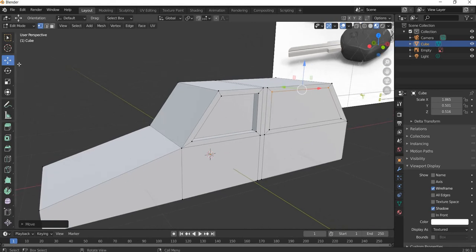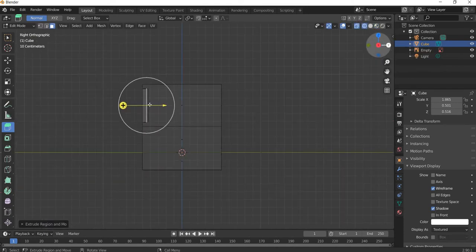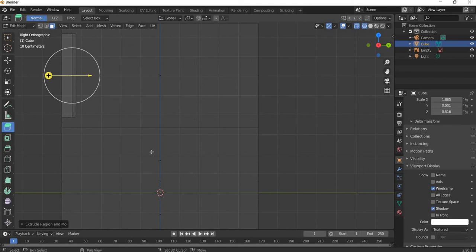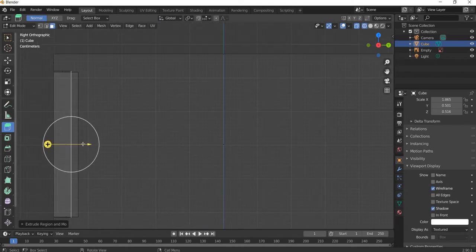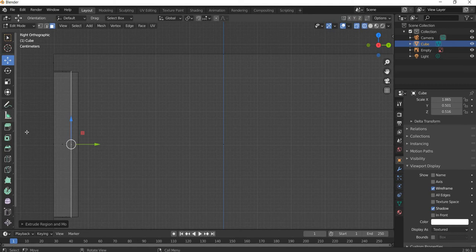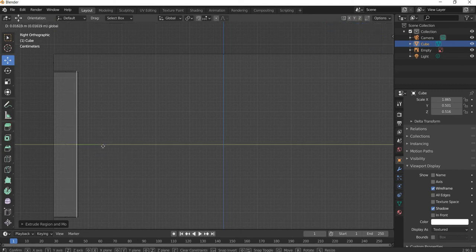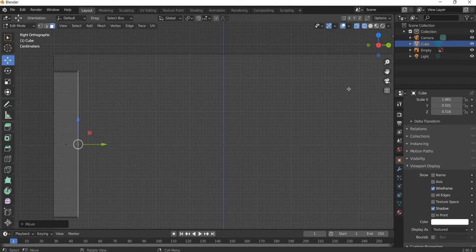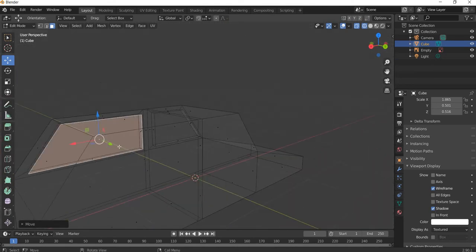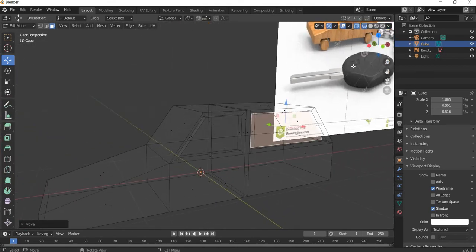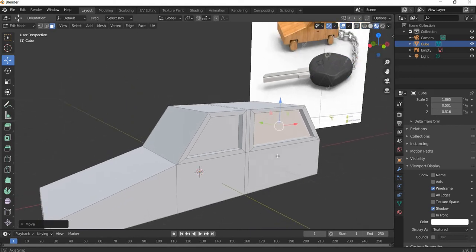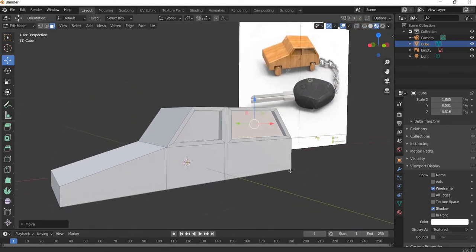We could have extruded these together to have even thickness, but we could extrude it, go to wireframe mode, go to the side view, then here we'll go to the move tool. Don't stay in extrude and try to adjust it, it will add more lines. So this way we can make sure that both are extruded inside the same distance. Alright, so that is done.